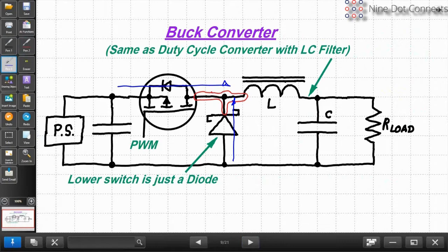Well, assuming the power supply is fairly far away and there's inductance and things in the line, it's going to be primarily drawn through a bypass capacitor. You try to keep that bypass capacitor and/or input filtering close to this device. Otherwise, all that switching noise is routing back through the entire board back to the power supply. That's where it has to come from, and hence it's going to be coupling into all sorts of other things. When it's not, it's just going to be basically coming up from ground.